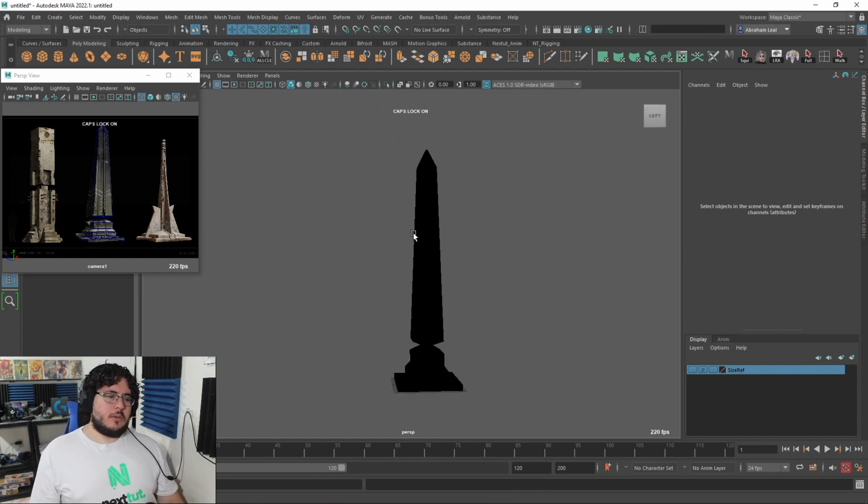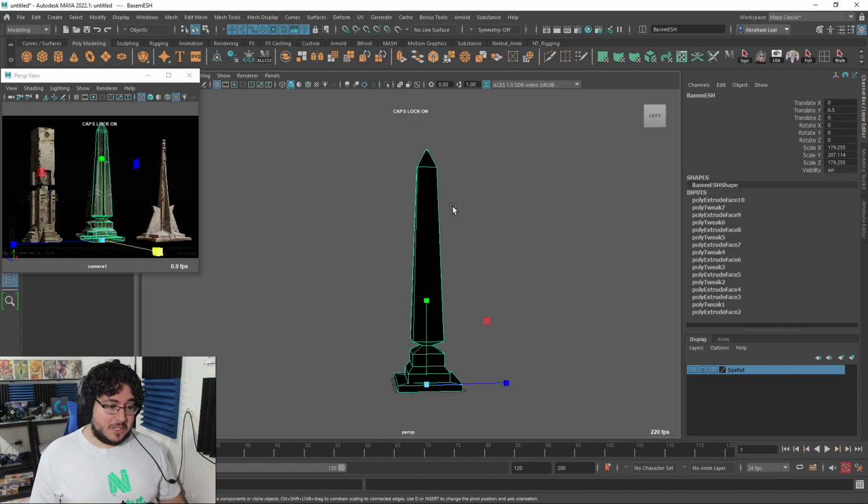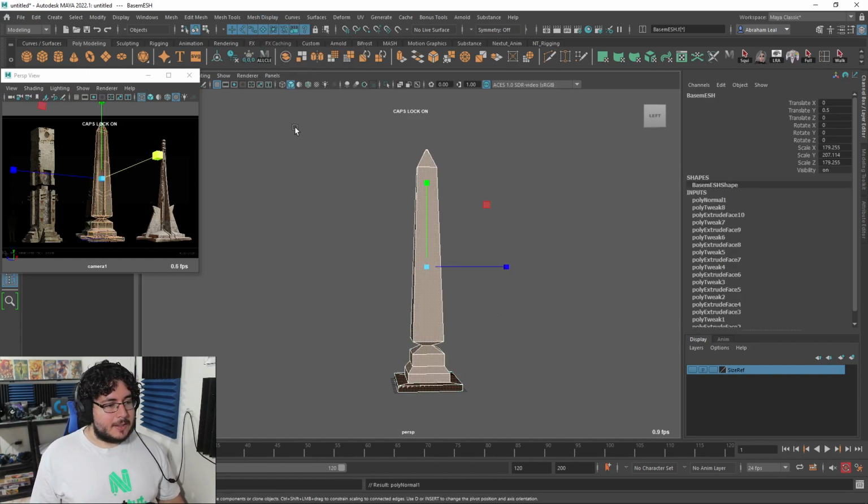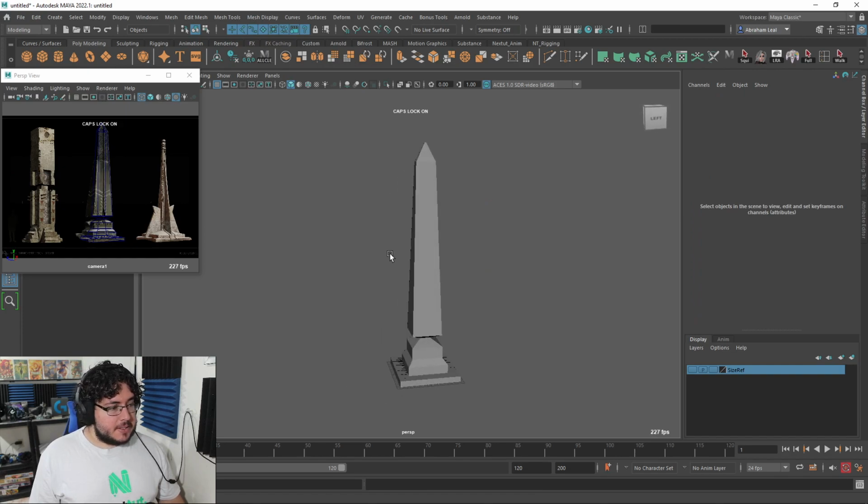Now you might be asking, why are you using the light mode? This is not light mode. This is actually the geometry that's reversed, which is bad. So I'm gonna go mesh display and hit reverse so that the polygons are now facing the proper side.